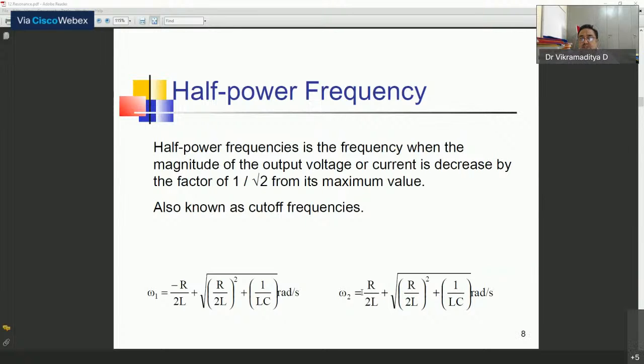I was talking about some terms related to the resonance phenomena in a series circuit. We were talking about the half power frequency and the resonance condition. In fact, resonance condition, the misnomer is that in an electrical circuit it is considered where voltage or current is maximum. No, it is not so. The power is maximum. We are mainly concerned with power, and we assume that the gain which you have obtained will remain constant at half power frequency also.